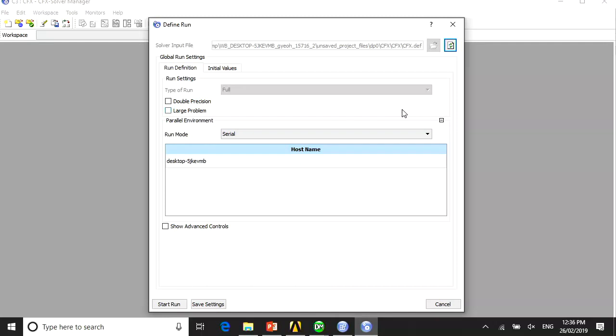But hold on there. 16 decimals means that if you have a lot of mesh, it will take longer to solve your problem, so you've got to weigh that out. It also depends on how many elements you have. If you have 10 million mesh, double precision will take much longer, because you're occupying more of the virtual memory and need to store these values while the code performs all the calculations.